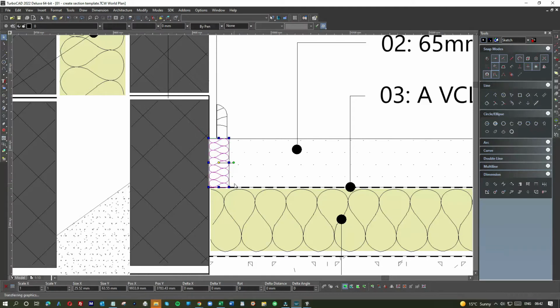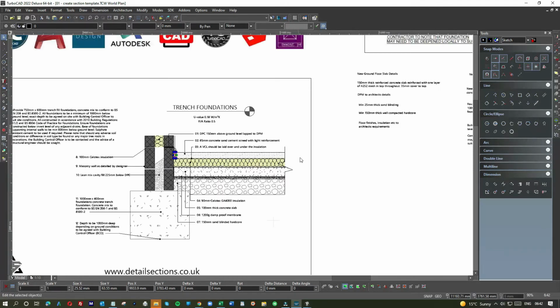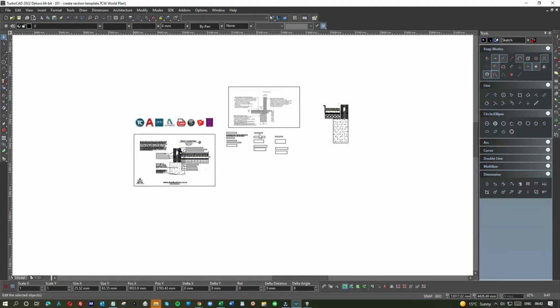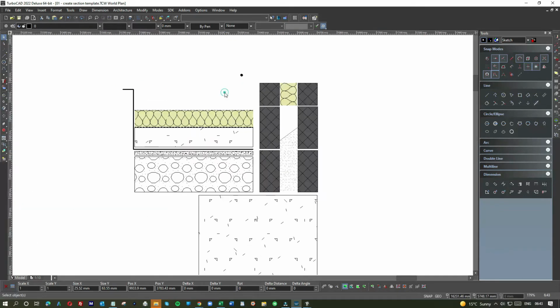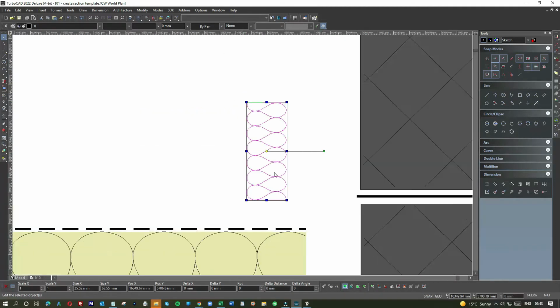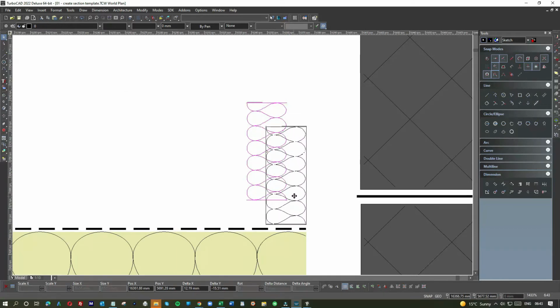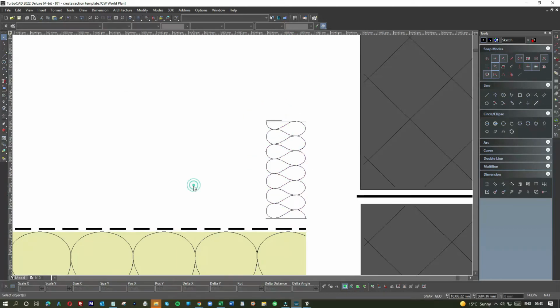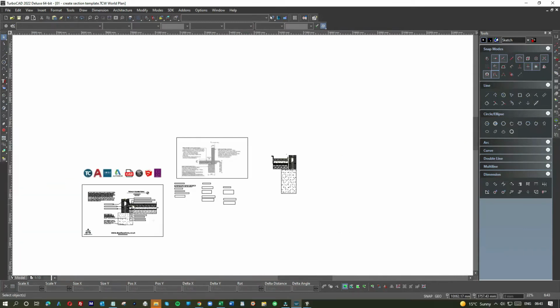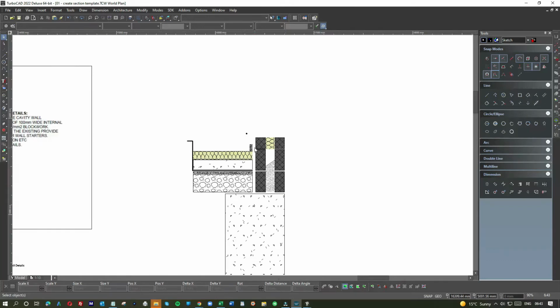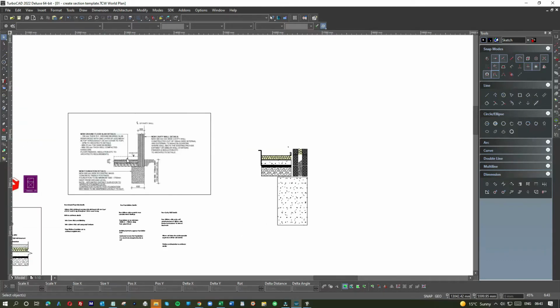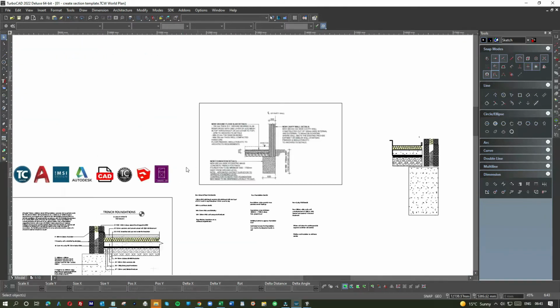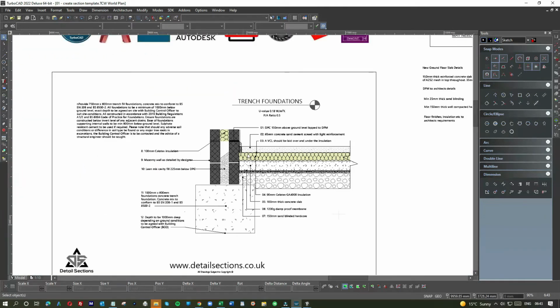That's very important. That's to make sure that you don't have a void, meaning insulation loss, which often happens at the edges. So that's an essential little piece here, or you're going to have heat loss on that area going into the brick or going into the block. So it's important that you just do exactly as it is here.